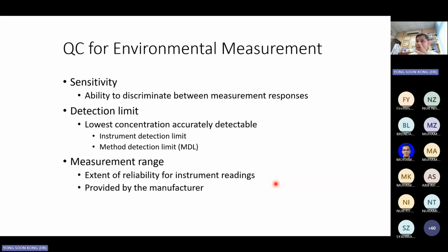I think I will stop for a while and ask the water group. Water group people, okay. Let's say that river is class 1, very healthy. If the river is very healthy, what do you expect of the DO reading? Is it going to be very high or very low? Dissolved oxygen, if it's class 1. What do you think? Water group or anybody, because you also take water resource technology. Class 1, not polluted. How is the DO? High or low? High. It should be, right? High. Okay, there you go.